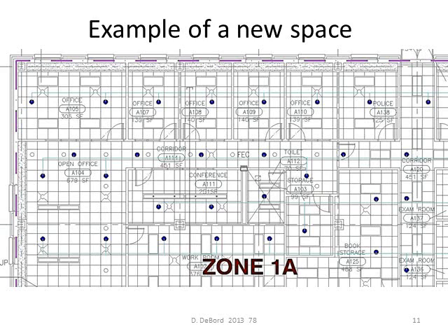Plans change. Also, we see that our sprinkler piping is running over the diffusers. If you look along the top row of offices, 105 through 138, normally you would keep your sprinklers off of there. There might be a lot of room up above, but maybe not. And we could easily avoid that conflict.